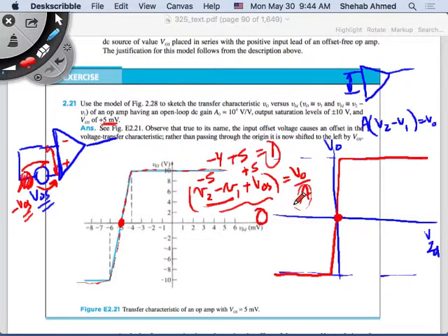Here we deal with this from an application perspective. And then we dig a little bit deeper and see, okay, we will deal with these bias currents. We will see that when we design transistor circuits, this is where this bias current is coming from. So here I will just show that there's bias current. There's offset voltage, right? The offset voltage is dealt with in chapter 12 in a lot of detail. Yes, sir.